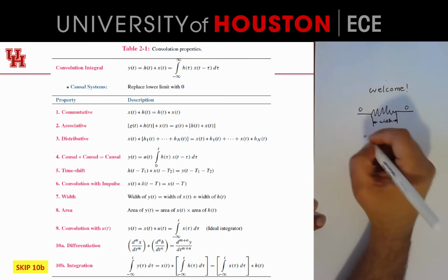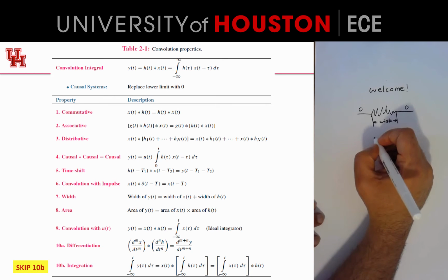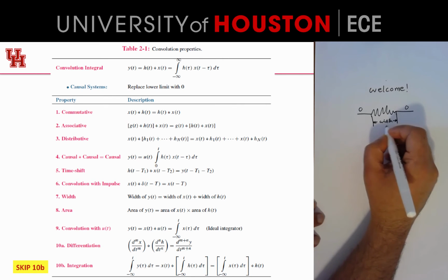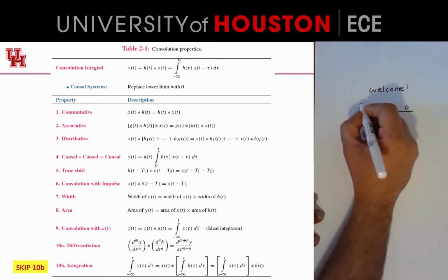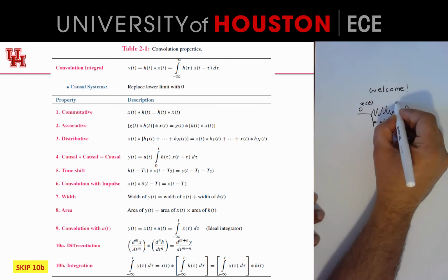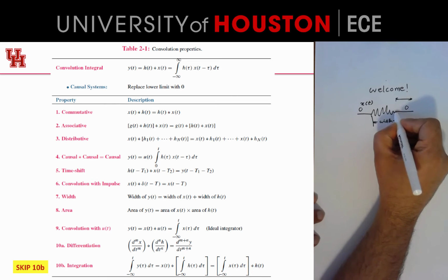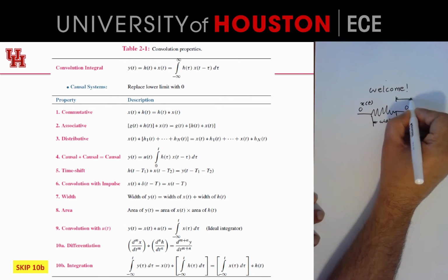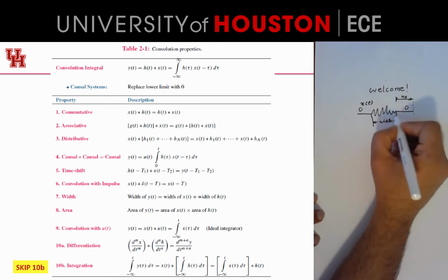For these types of signals, the convolution operation simply adds up the widths. It makes sense: if this was x of t, and h of t lasted that long, then the last of x of t will still produce an output until the point at which the impulse response width lasts.